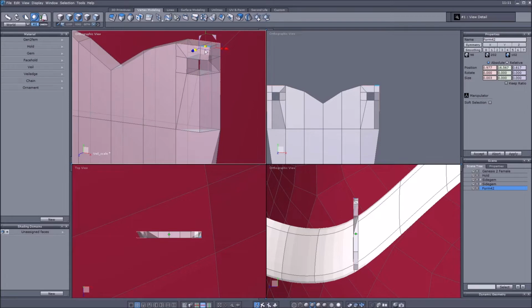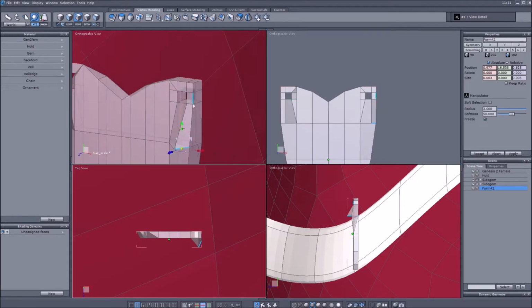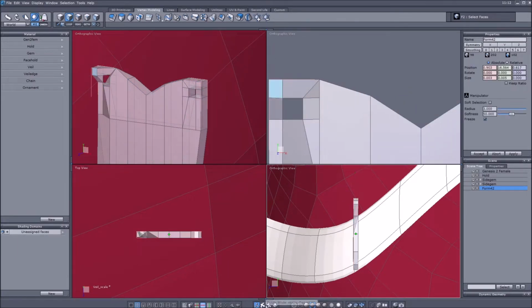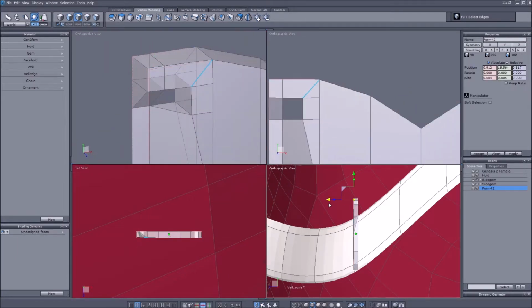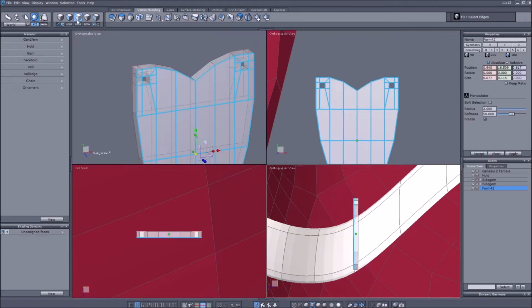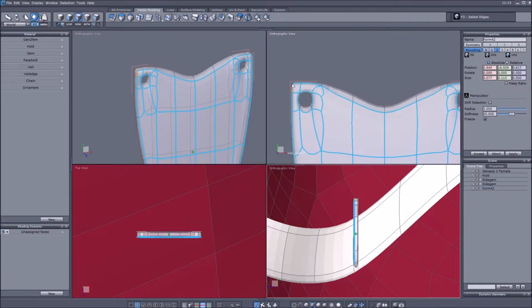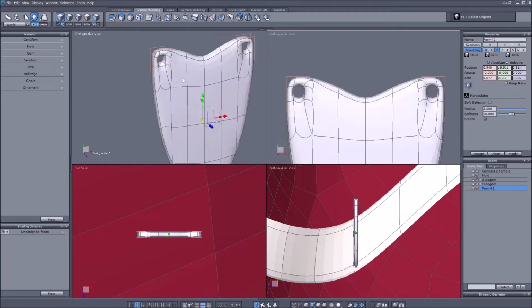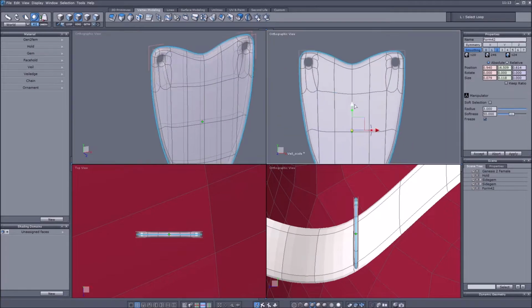This happens sometimes, that due to a calculating error, or due to creating artificial lines in the whole object, the thickening tool gets a little bit weird. But as you can see, this is fixable quite easily.